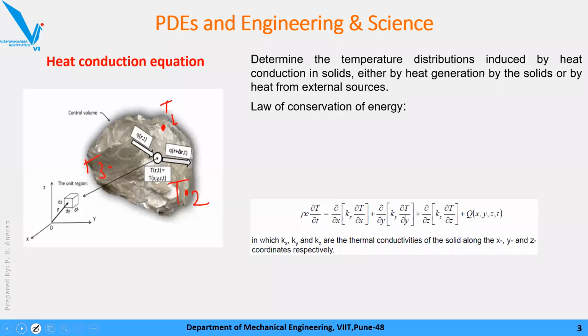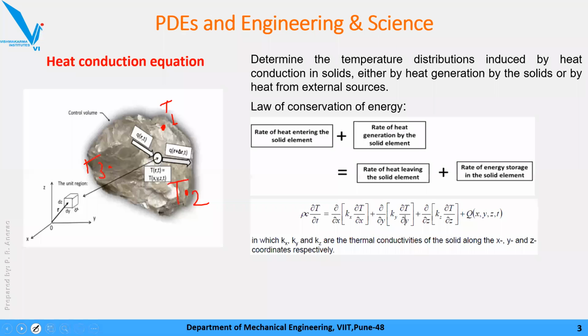Now, by applying the law of conservation of energy, that means we are going to balance the energy. So the rate of heat supplied plus the rate of heat generated should be equal to the rate of heat leaving the system, or leaving the solid element, plus the rate of energy which is stored within the solid. Okay, so this is your balancing equation.